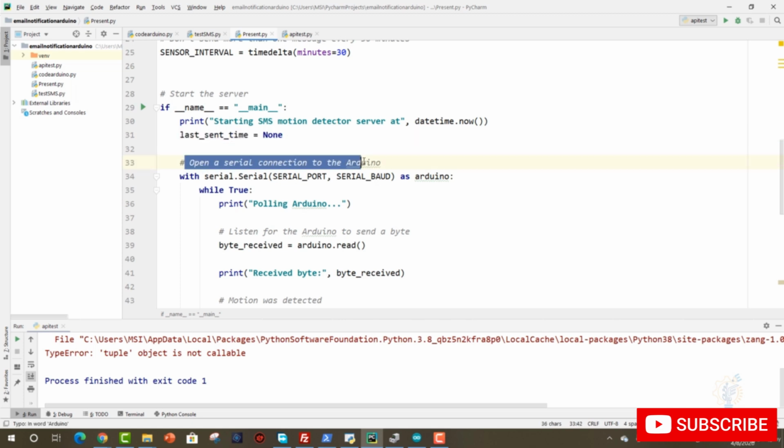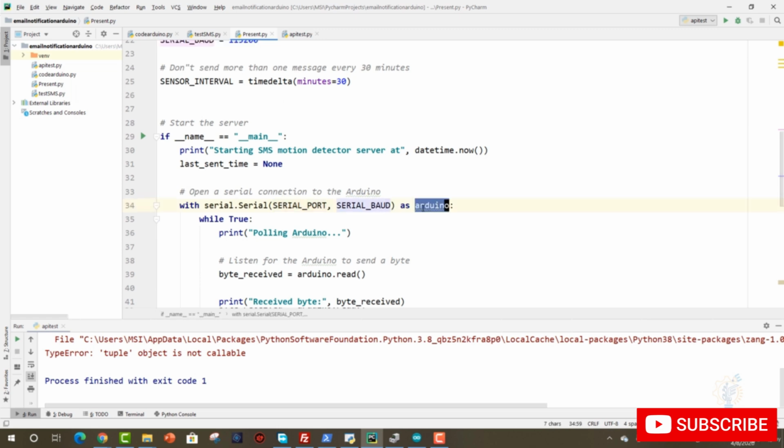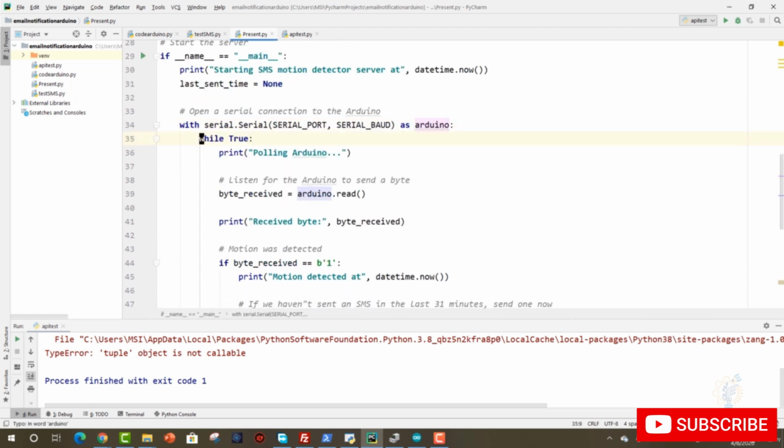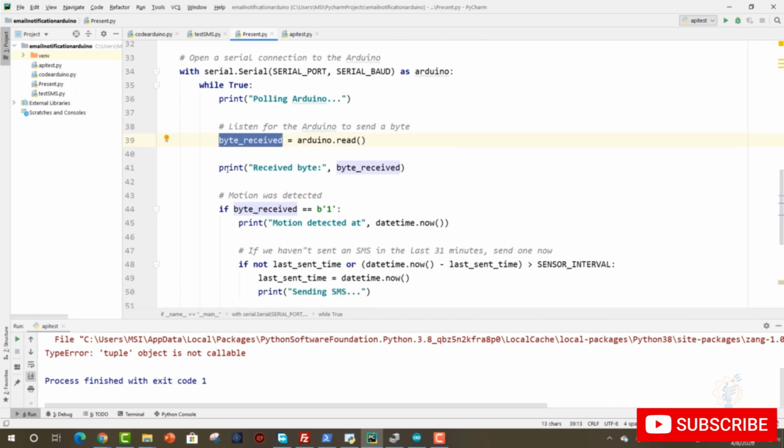Now this section is for opening up a serial connection to the Arduino. This is the serial port variable, and this is the baud rate that we already defined here, and we called it Arduino. Now while true, while there is serial communication happening, print polling Arduino, which basically means that we are communicating with Arduino and trying to pull data from it. Here we are reading the incoming data via the serial port and storing it in the byte received variable, and here we are printing the byte received on the serial monitor window, basically here.